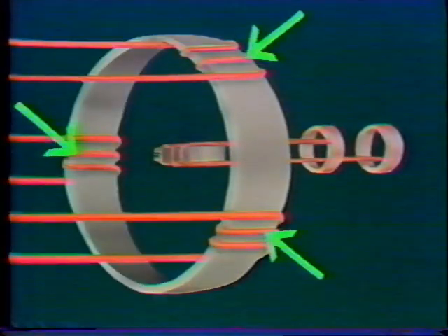Remember how a generator works? You know the rotor must be turning to generate voltage. The mechanical force to turn the rotor can be provided by a turbine, a motor, or even falling water. It doesn't much matter as long as the rotor turns. So, here we have the 3 things necessary to induce a voltage: a magnetic field from the electromagnet on the rotor, relative motion from the turning rotor, and a conductor, which is the windings on the stator.